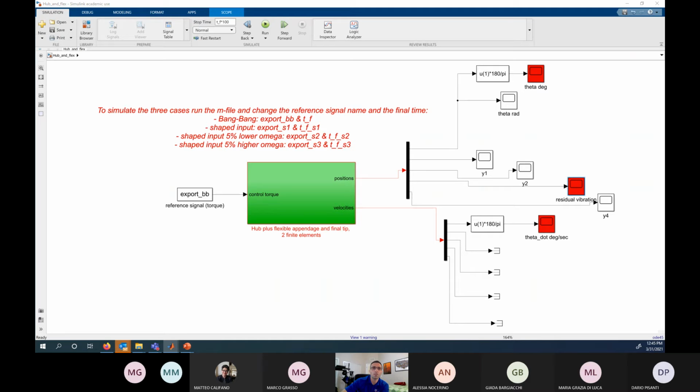And that's because there is a residual vibration that I haven't even considered. As I said, in the equations of motion, you have those terms m theta q or m q theta in the mass matrix, that are basically telling you, okay, I apply a torque to the hub that is going to excite my flexible link, but vice versa, the flexible link is moving back and forth, and that is going to apply a torque on the hub, and that's why things are not going anywhere. So this is the bang.